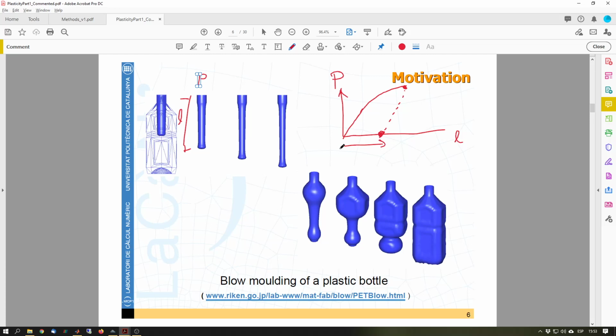So call this the persistent length that we have, even if I remove the pressure inside. In fact, I would keep remaining a certain length, let's call it the persistent length. We can also denote it as a plastic length because it's a remaining length, so it doesn't go back. Going back through that curve would be non-linear elasticity. If I go back through another curve, that would be a signal of plastic deformation. Plastic deformation means what remains for zero loading.